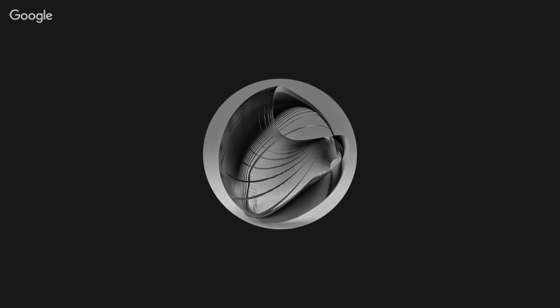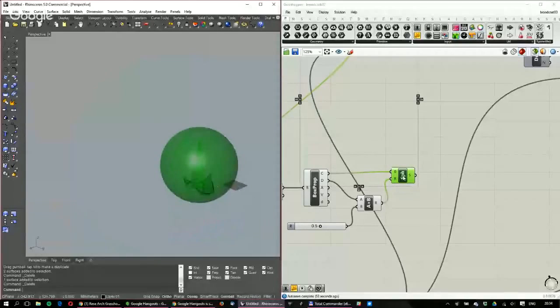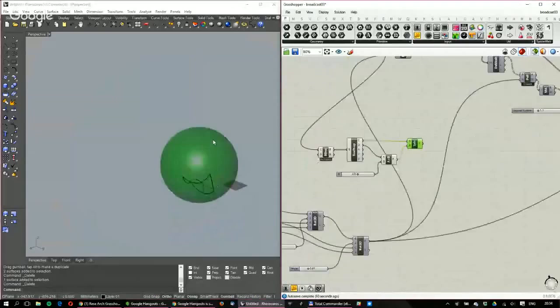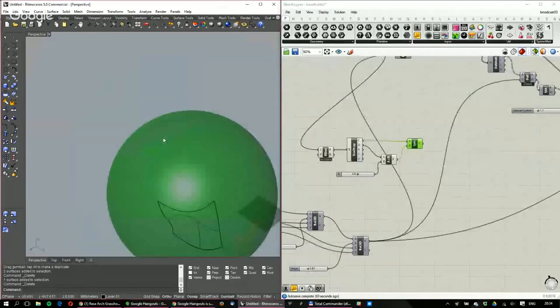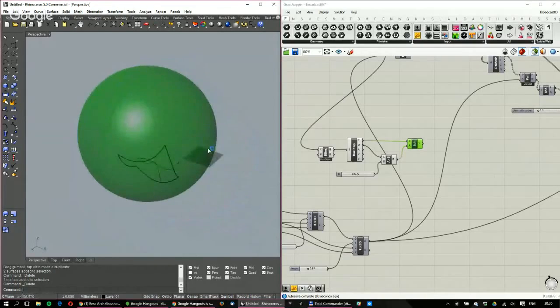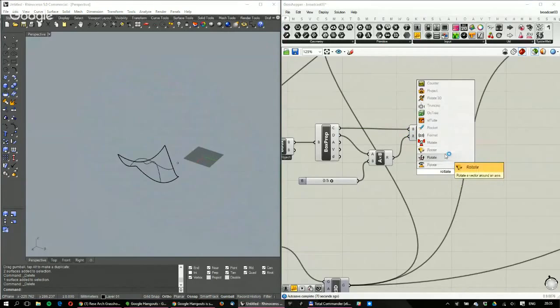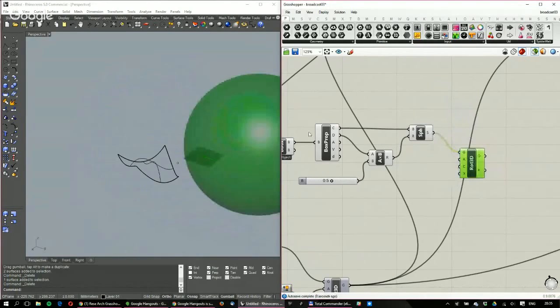The problem with the sphere in Grasshopper is that if we select a random point on a sphere, they're much more dense at the poles and much less on the sides. Because it's basically a wrapped surface, it's very dense here and very empty or deserted on the equator. So what I would do also is that I would rotate the sphere randomly so that we don't have the growth only from the top and bottom. Rotate the sphere geometry. This is the central point.